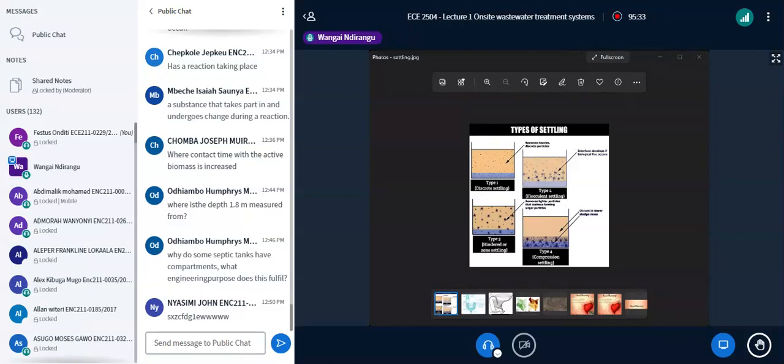Each of these has an implication. Suffice to say for now that compression settling is about squeezing the water out. Like we do in a building. When we build a structure, it settles by compression, by driving out the water between the soil particles, or what we call consolidation.